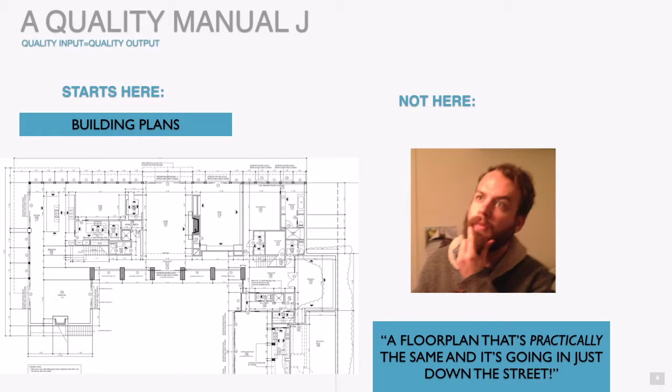You can sometimes deduce what your elevations look like more or less if you have a roof plan with overhangs, and if you have window dimensions printed on those floor plans. But windows being so important, it really helps to have those elevations so that you can get your projections or your overhangs for the windows, because that does have a very large impact sometimes on the load results. So we want to make sure that we're starting there and not just the best guess, right?